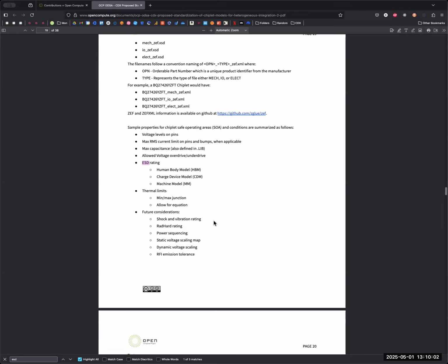Yeah, you are right. And they don't have the ionizers to take care of it. In hybrid bond, we have ionizers. So, like you said, basically the environment. And even after hybrid bonding, the bottommost die must have proper ESD protection.